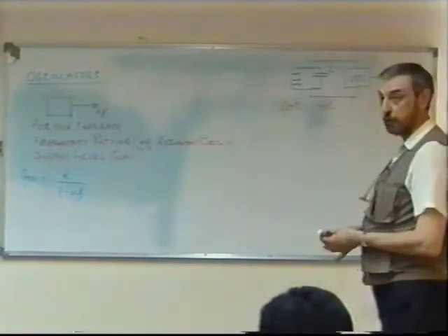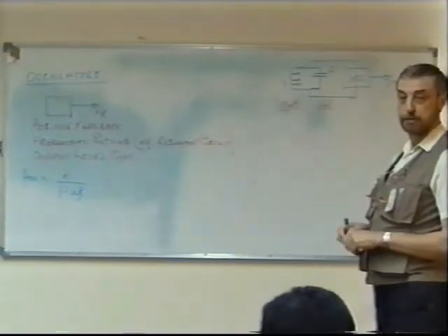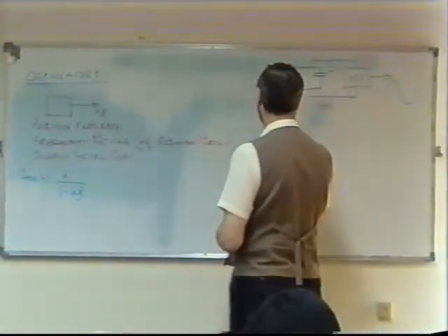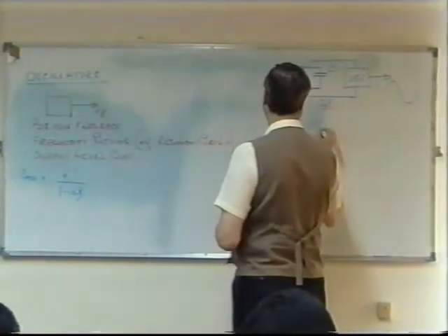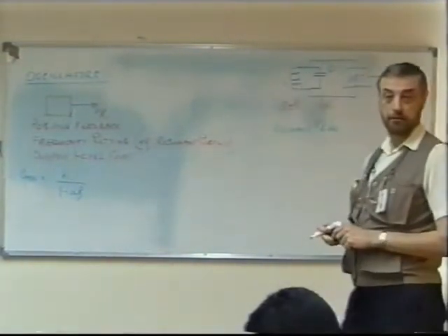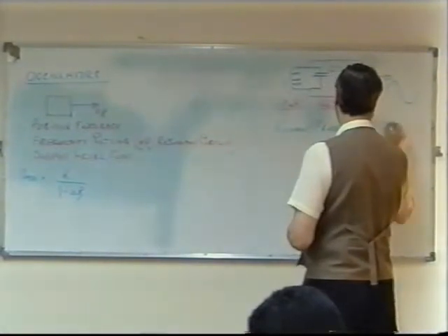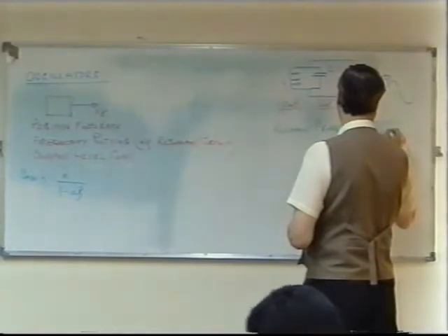Can you all remember the formula for this? For resonant frequency? We mentioned it yesterday. And it's the same formula for an oscillator, if you're going to use it. Resonant frequency. That's right, 1 over 2 pi times the root of L times C.